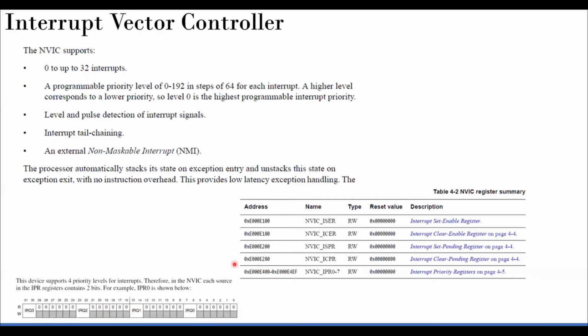And then if you see inside the NVIC, what is inside? There is a lot of logic circuit. In addition to that, it has 5 registers built into it. And see the location. So always go back to that memory map we have. And this is somewhere at the top of the memory map, towards the end, because the address location is somewhere around 0xE. So at 0xE000E100, we have a register named interrupt set enable register. What is inside this register? It has 32 bits. That means 32 interrupts or 32 locations, 0 to 31.